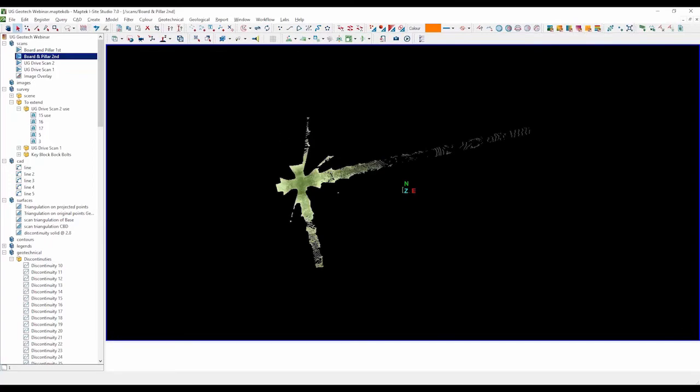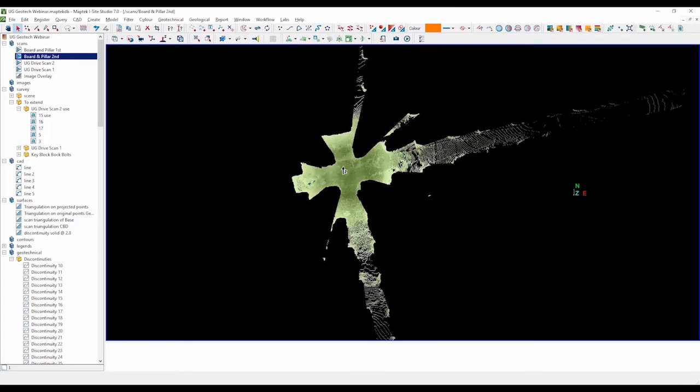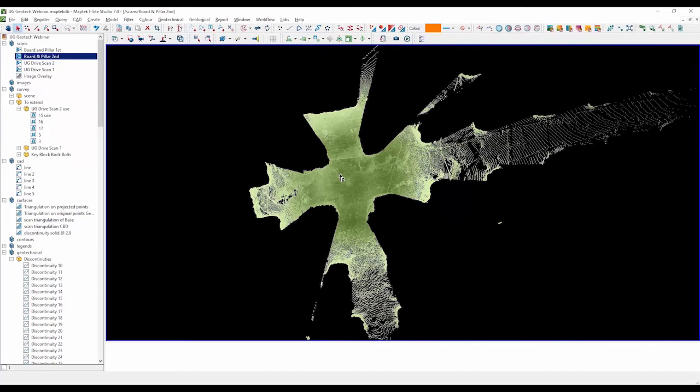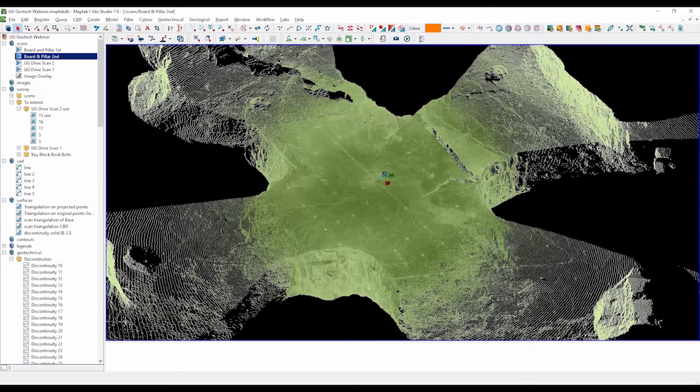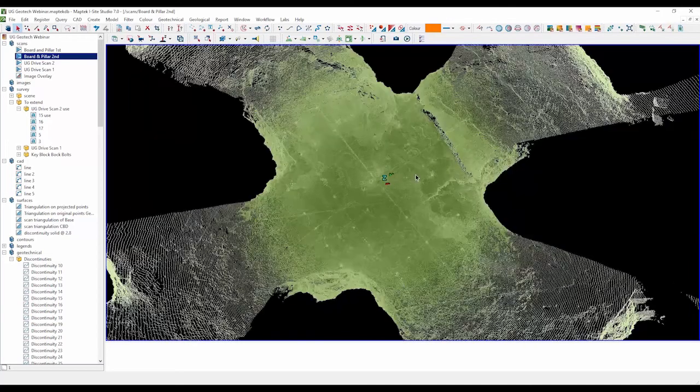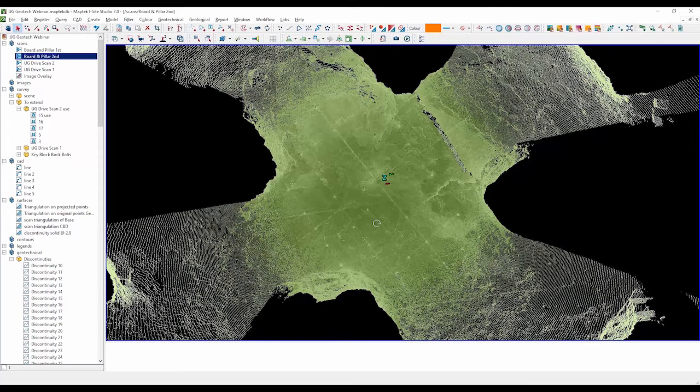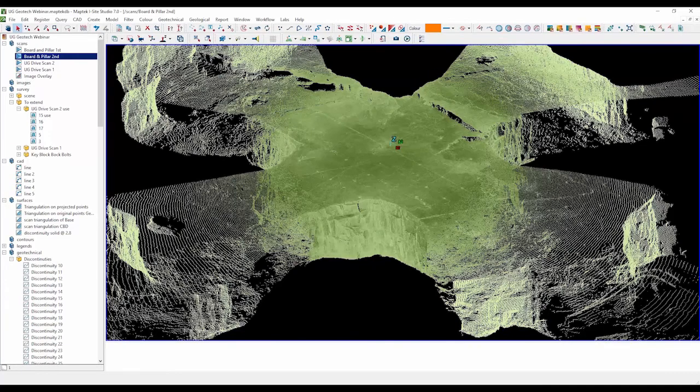What I'm going to show you here is the spalling rate over time. So how to analyze it effectively: if it's your normal board and pillar mines, you've got your pillars, you can do some analysis on those as well as your rib pillars, as well as any other sidewall components. This is quite nice to do some reconciliation in areas where you identify that there's been some high pressures either on the sigma 1 or sigma 3 component.